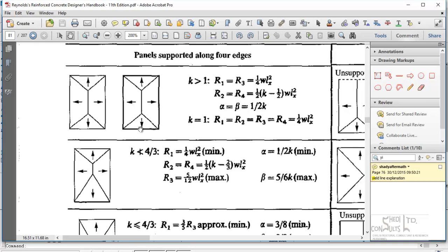So you have a yield line here, a yield line here, a yield line here, another yield line at the edges. Conversely, yield lines also form at the intersection between boundary edges. So you have a boundary edge, so these are another yield line. These are another yield line, and a yield line terminates at their intersection. So you see that this terminates there. So this automatically becomes the yield line formation.